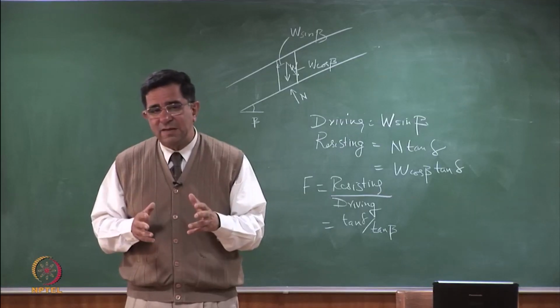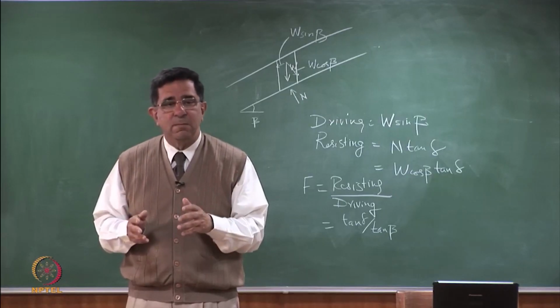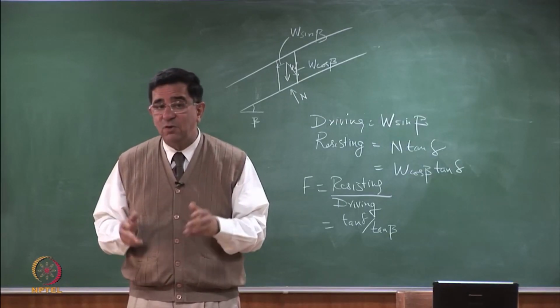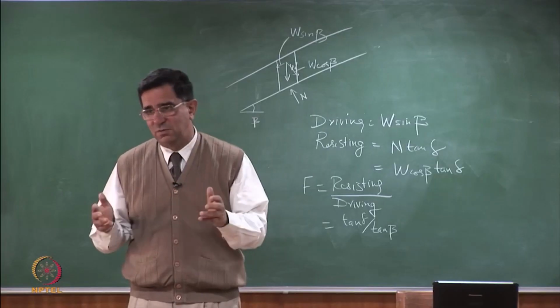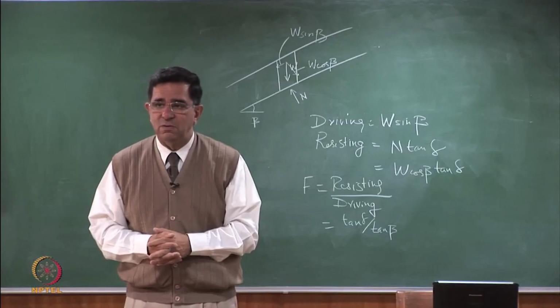So most of the analysis is like soils, except for the interfaces, which is like failure parallel to the outer slopes. And in that, now you'll start to get 2 wedge also. We've just done an infinite slope analysis, but you can have a 2 wedge and a 3 wedge method also.